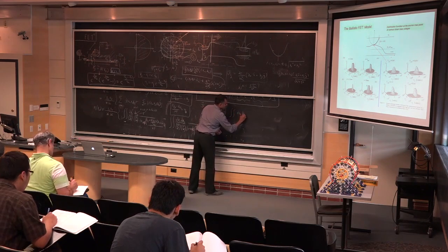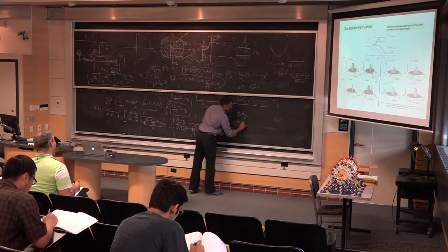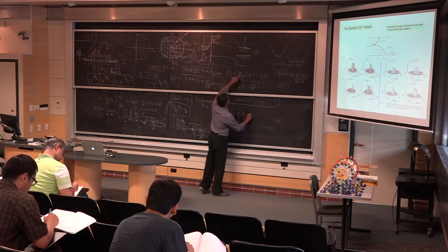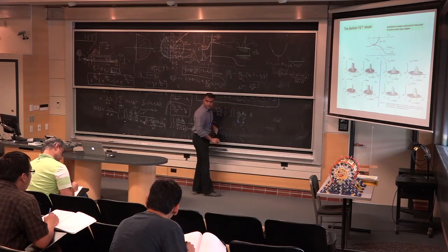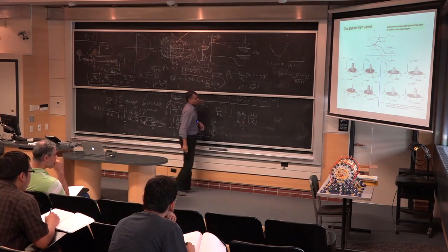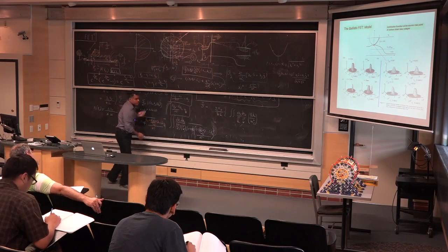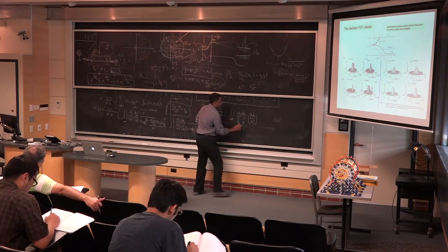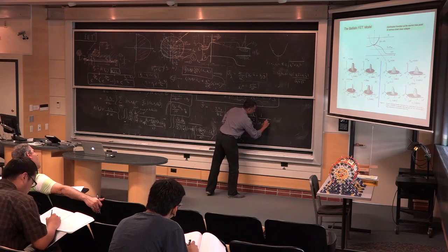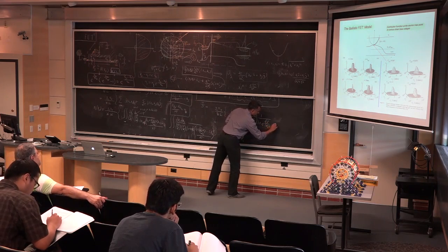Again, dkx, dky, always 2 pi over L, 2 pi over width, we're summing over modes. And the x-directed velocity is h bar times kx over m star. H bar times kx over m star of the conduction band. This times our old Fermi-Dirac distribution, exactly the same thing here, with the source function for the right-going carrier. So these are the carriers going to the right. And this is, again, 1 over 1 plus e to the power. I'll write it in the units we used earlier, m star c over kT minus eta sub source.